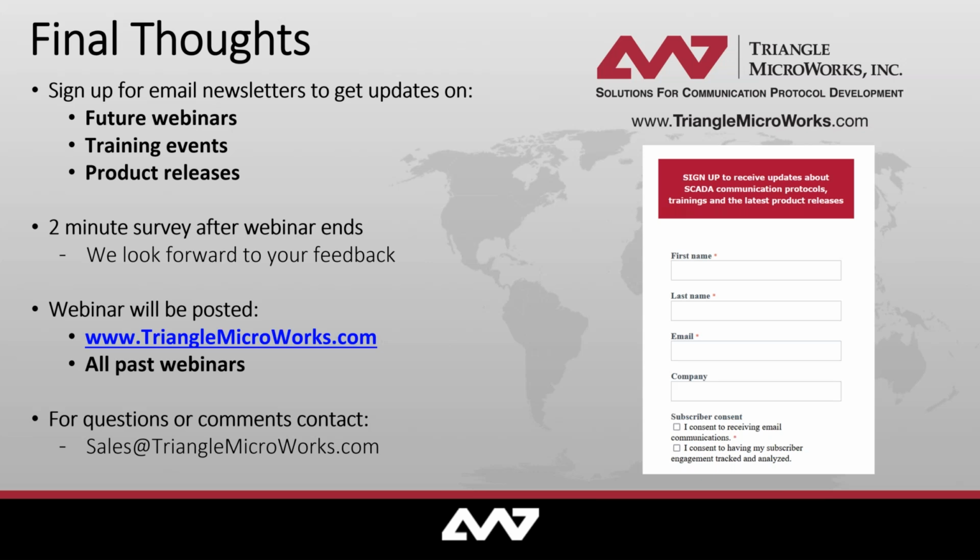Well, I'll take a stab at that. Matt, feel free to jump in. In general, I would say that they just have two different roles, right? GOOSE is going to replace the communications, or the signal exchange, that was typically done over a wire. So it's not limited to a binary, like you would have on a wire, where you can just send an on or an off. But you can send analog values as well, or double bits, things like that.